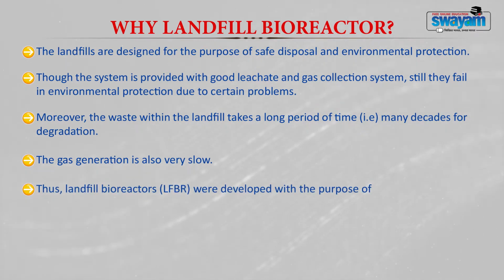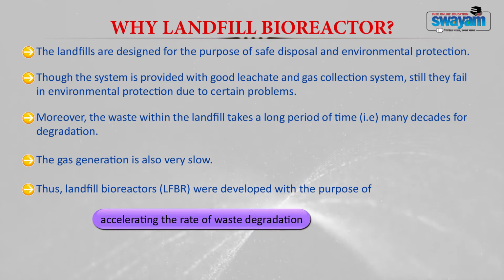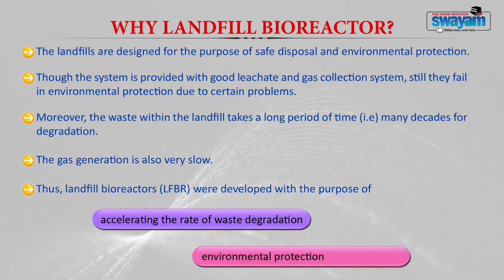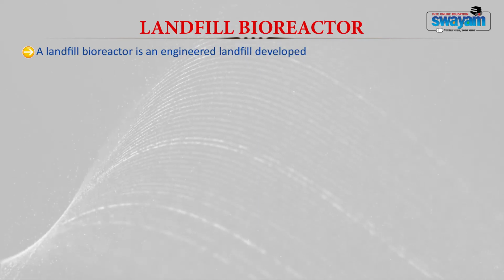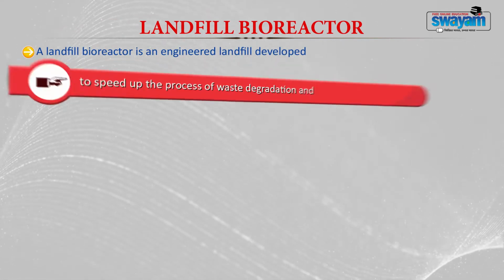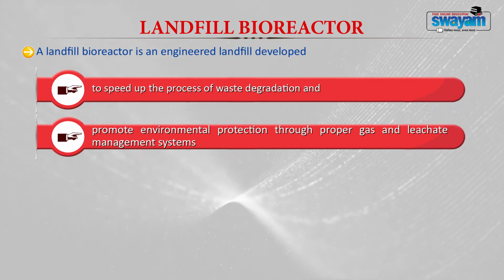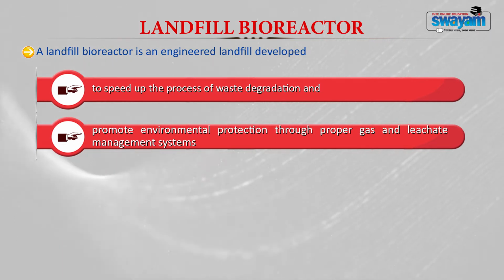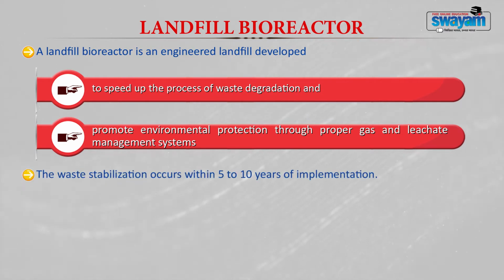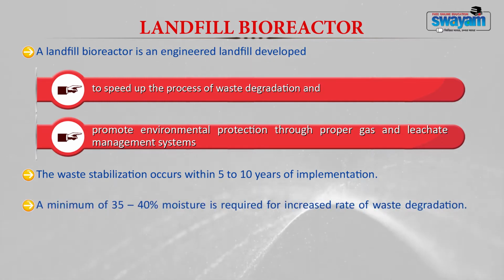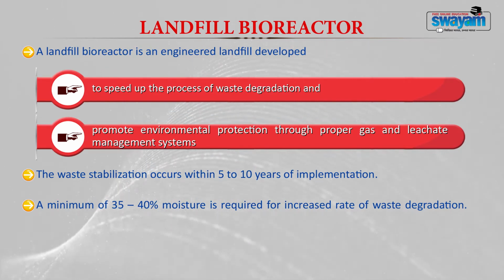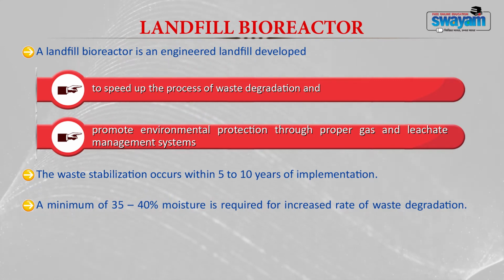Thus, the concept of landfill bioreactors was developed with the purpose of, one, accelerating the rate of degradation, and two, environmental protection. Landfill bioreactors are again engineered structures developed to speed up the process of waste degradation and to promote environmental protection through proper gas and leachate management systems. Within a landfill bioreactor, the waste gets stabilized much faster, within 5 to 10 years of loading. A minimum of 35 to 40% moisture is required for the waste to degrade at a faster rate within 5 to 10 years.